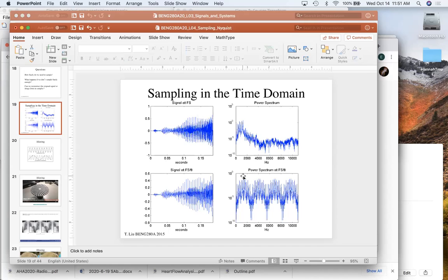Yeah, so checking whether you're undersampled is often about looking at this and asking what is the separation of these, and what is the power in the part of the spectrum where they're overlapping. So this is not really an accurate representation of the underlying frequencies in this signal, because this is the accurate representation of what's going on out there. It looks about the same until you get here.